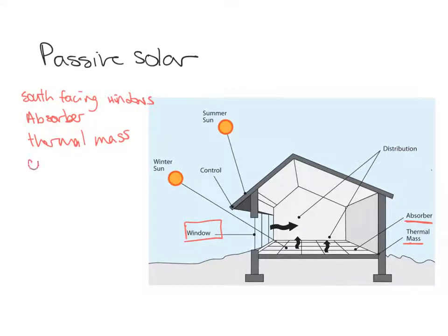Another piece of passive design is circulation or ventilation. So you want the heat or cooling to be circulated through natural conduction, convection, and radiation. Part of this can be taking advantage of prevailing winds. So if prevailing winds blow from an east to west direction, you would want windows that could open on the eastern and western sides of the houses to allow for that airflow in cooling the house.